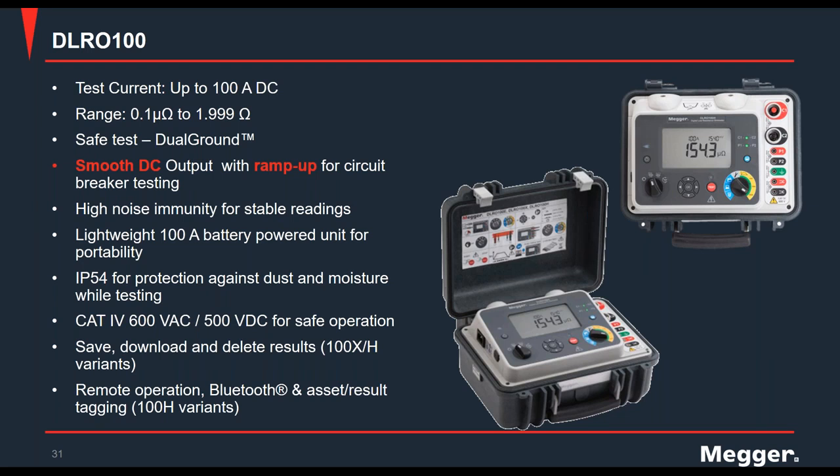It has high noise immunity so that you get stable readings. And for a test instrument that provides 100 amps, it's lightweight. It is IP54 rated for protection against dust and moisture while testing. And it is Cat4 600 volts AC or 500 volts DC. It's intrinsically safe for operation. And you can save, download, and delete results in the 100X and the 100H variants. And you can remotely operate, and it has Bluetooth and asset result tracking.